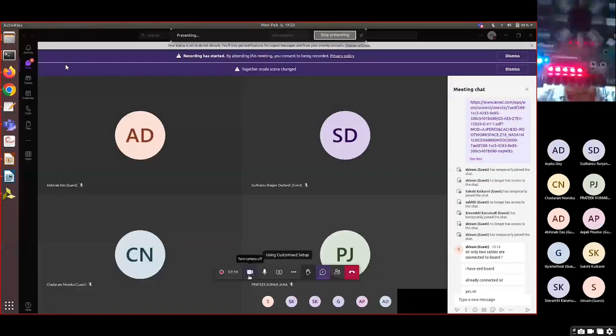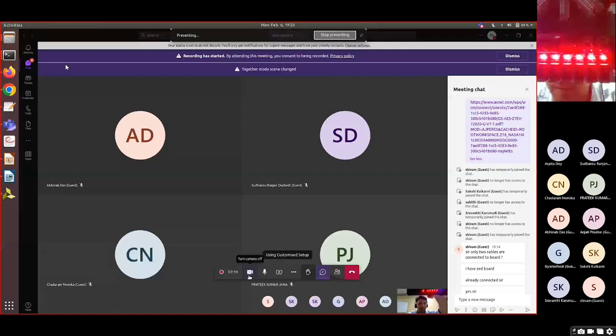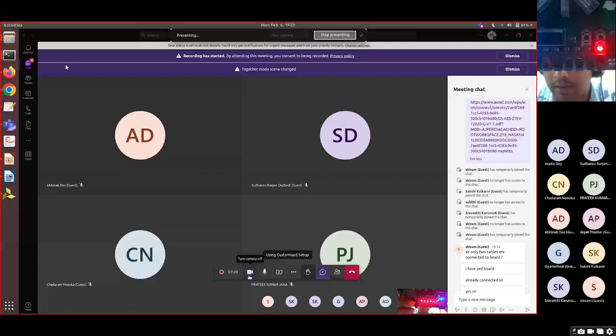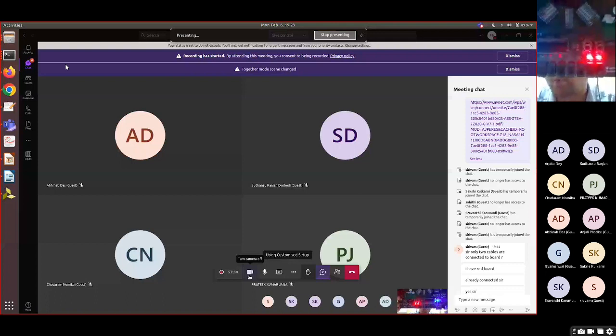Once I have programmed, you can see here, I'm switching on my video again. Yeah, so you can see here, this is the reset, an asynchronous reset, right? By default, it is down count, so I'm making it up. I'm switching it and resetting. You can see that close to every second, it's not a real time clock, but close to 1 second, the count is incrementing, right?